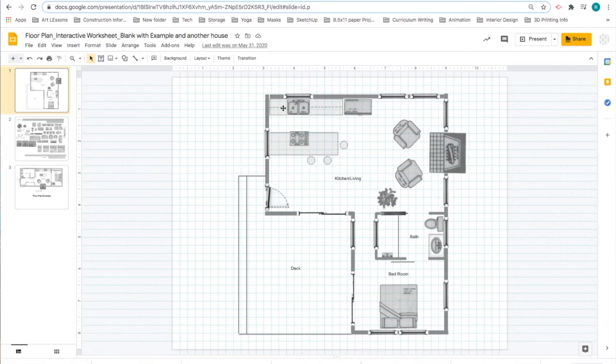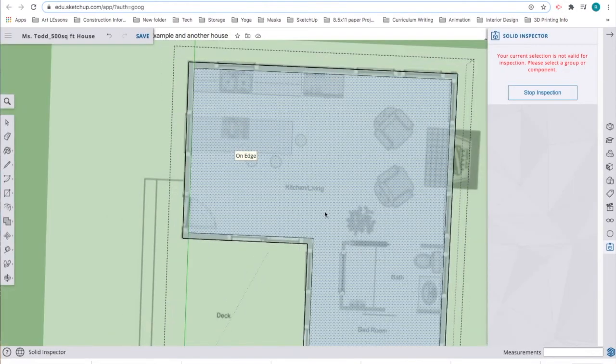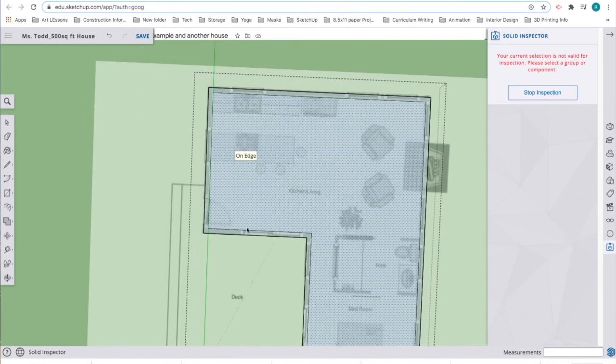We don't necessarily know how tall they're going to be, but we do know that they're 3 feet wide. The doors: I have a swinging hinge door here that's about 3 feet. I have a 6-foot slider here, and I've got my opening for my barn door and also my pocket door. In the floor plan, I'm going to start to lay out the interior walls and put in the areas where my doors and my windows are going to go. Let's start now with my bathroom because those are really the only interior walls that I have.